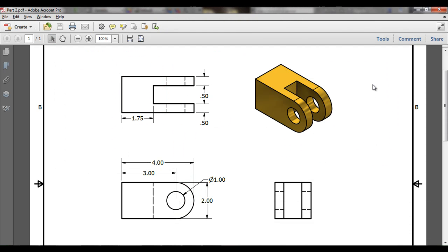So far, this is what our shape looks like. You might notice it looks a bit different from this because this shape has this cutaway here. So to do that, we need to make a little cutaway that gives you 1/2 of an inch of material here on this side, 1/2 of an inch of material here on this side, and it's 1 3/4 inches away from that back edge of the part.